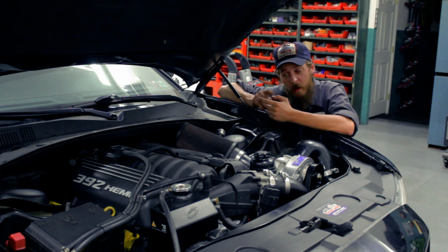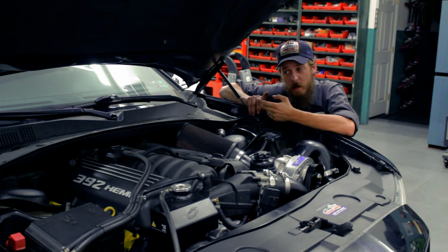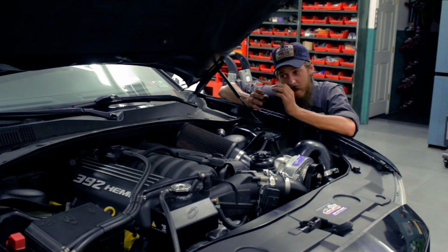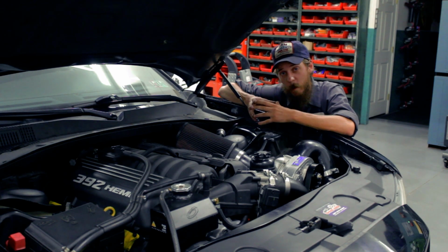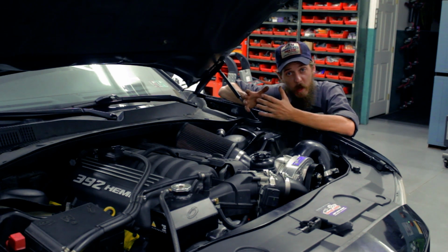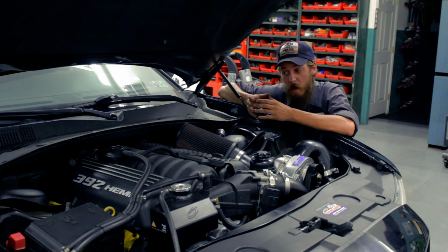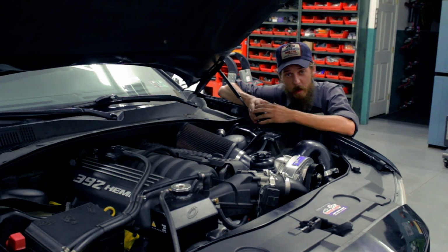In this case, we have the transmission controller, the selector lever assembly, which is our actual transmission shifter in the center console, the PCM, the BCM, and the RF hub were all seeing a park neutral status that they agreed with. The only difference was that in-series temperature switch/sensor was not going to system voltage when it was intended to in park or neutral, which would be a plausibility check within the software. So instead of looking at all the other data, the instrument cluster also agreed, because it's a bus input.